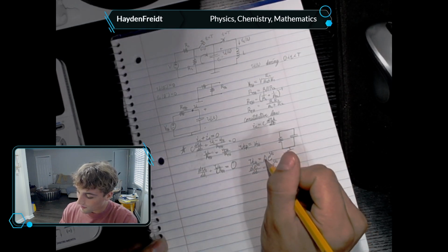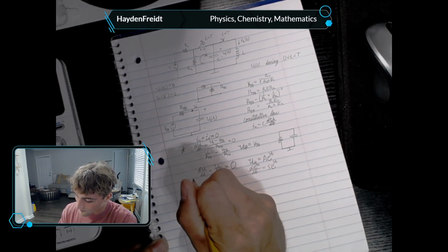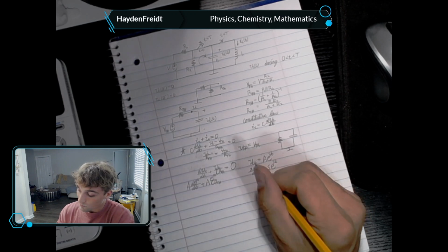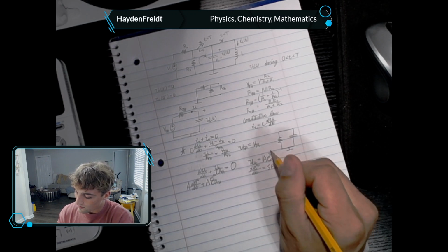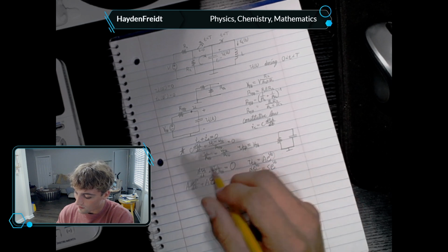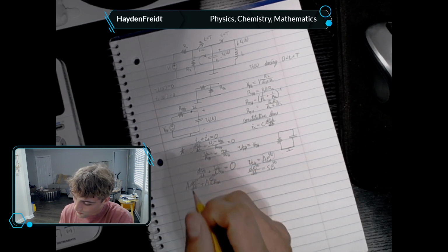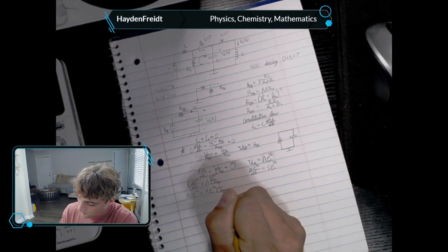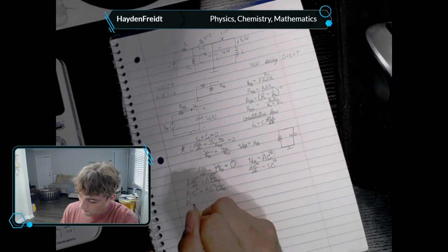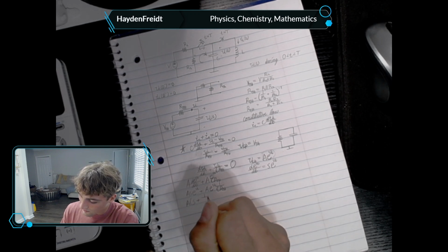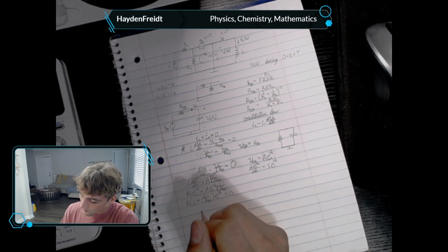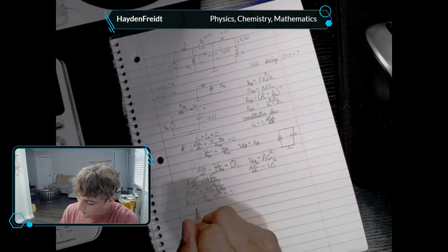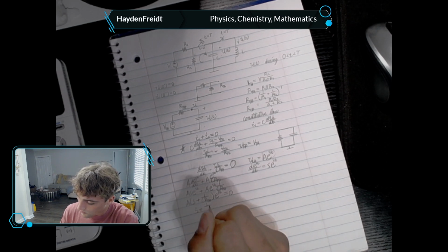All right, so we're going to plug this solution into the problem. I plugged this in everywhere there was a VC. So as I said before, we're going to have A times S e to the power of St. And I simply took it out of the numerator. A, and that leaves us with S. This side is going to leave us with 1 over C times RTH. Now we're going to take everything inside the parentheses and set it equal to 0. And so that's just going to mean S equals negative 1 over C times RTH.